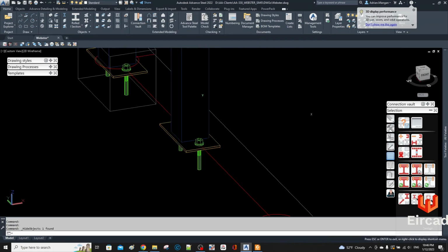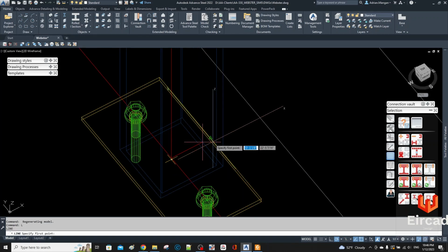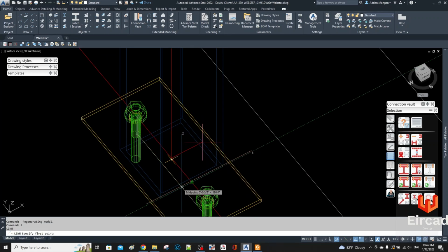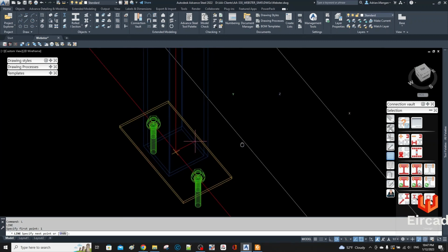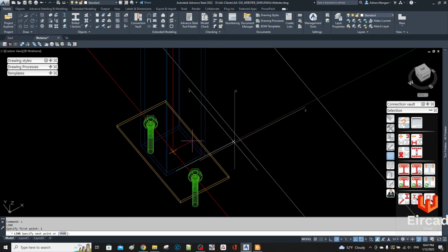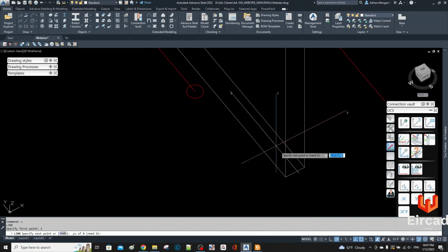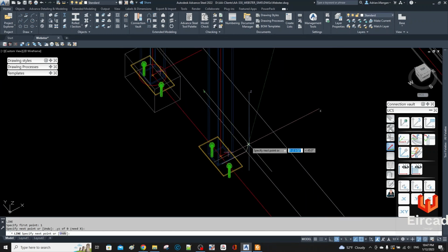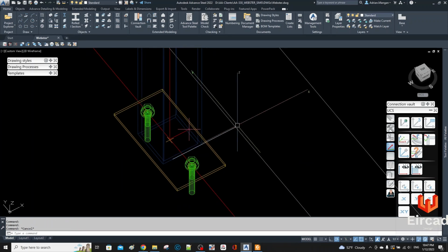I'm gonna hide that. So I want a bent plate going from here onto that, so it's 1/4 inch bent plate. So I'm going to pick a line from 1 inch back, so I'm going to leave enough space to weld here, and I'm going to come across this way in the X direction to the corner of that wall. I think it should be 3.5 plus this 3 here. Yeah, so 6.5. And what we can do actually is we'll draw in a polyline, because sometimes they don't join.